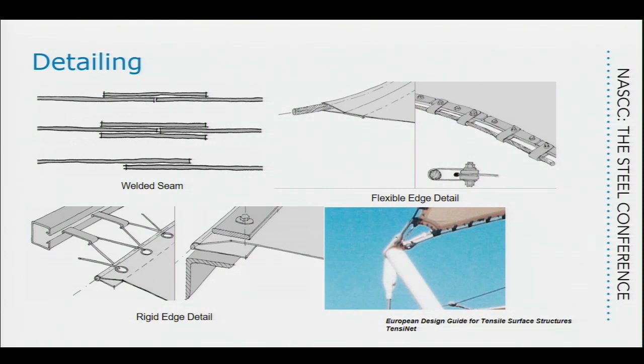I don't know if you've ever had the pleasure of designing a cable, but what happens is you design a cable and you have to design for a certain deflection. But if you end up with a cable that's not strong enough, and you put a stronger cable, well, that cable deflects now less, but it has a stronger force in it. So it's a very bad cyclical process.